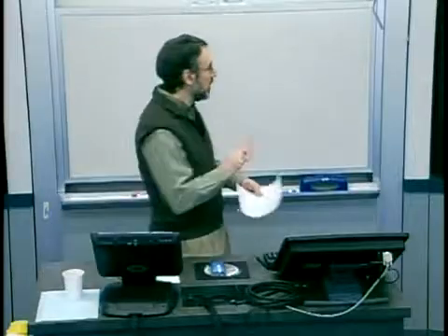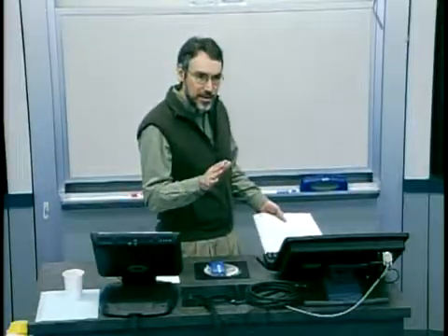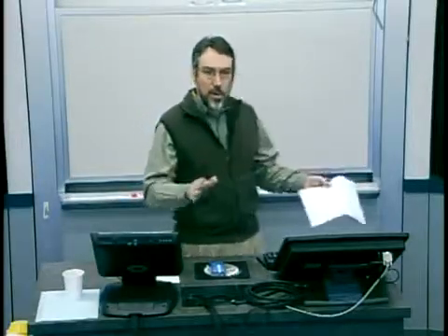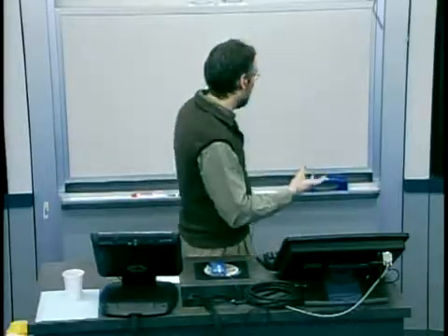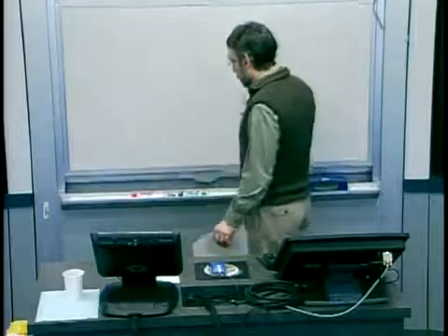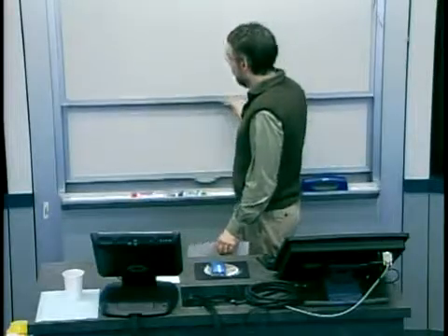So let me start again with the basic hypothesis test, because remember, all that a control chart is, is a running hypothesis test, where every new sample comes in, you're asking the test on the hypothesis: has the process shifted, or is it still my nominal distribution?